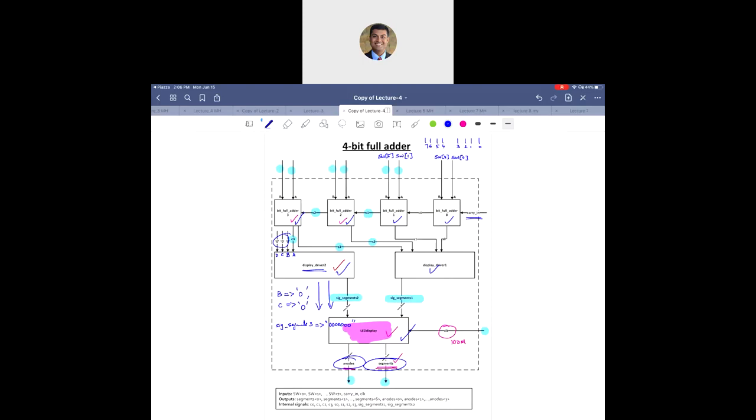And then after you're done with the top level VHDL design, you would write one XDC file for that top level, in which you have to connect these inputs and outputs to something physical.